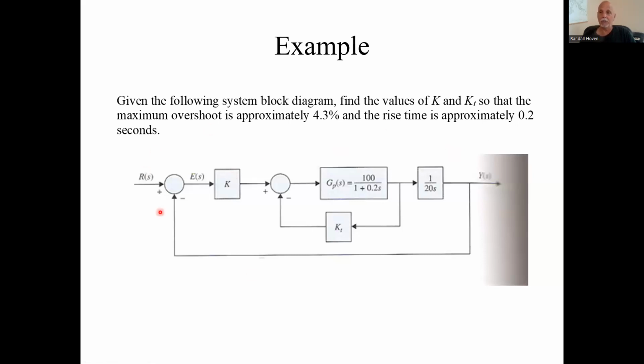The first thing we're going to have to do is come up with a transfer function. And let's hope it's a second order system, or else we don't know how to deal with it yet. I'll go through a review of Mason's rule to get there. There's only one forward path, straight down the line here, because all the other paths are feedbacks. And I see two loops. They both touch the forward path. That's good news. That means those minor determinants are just one.